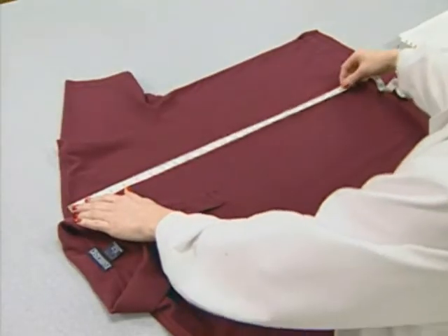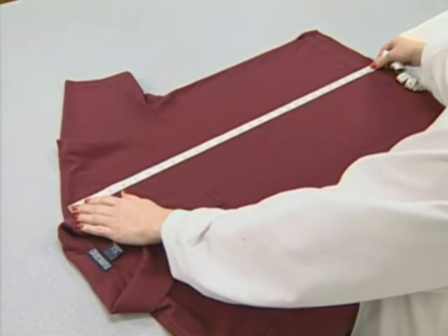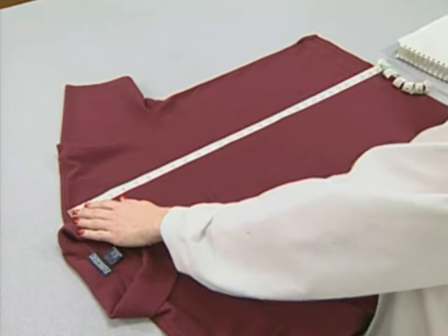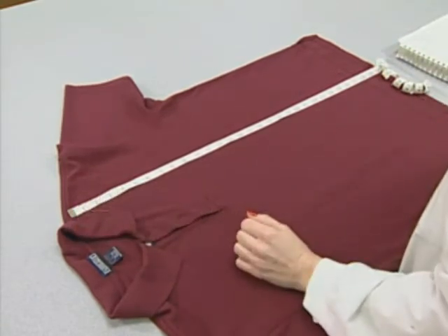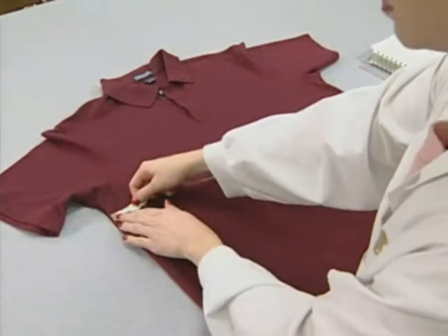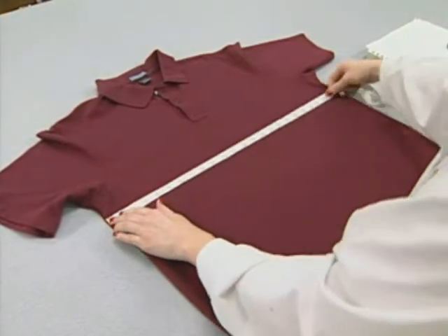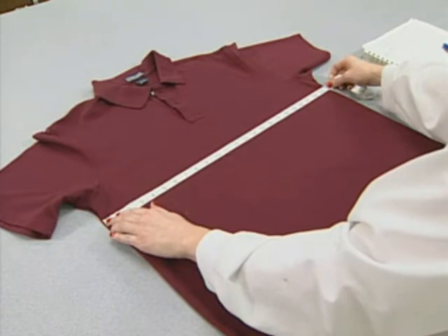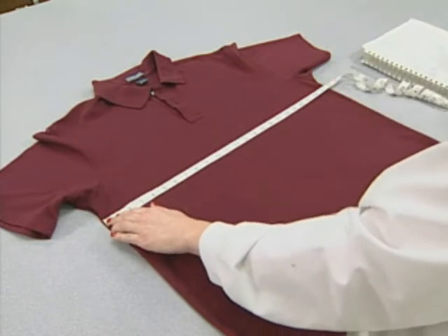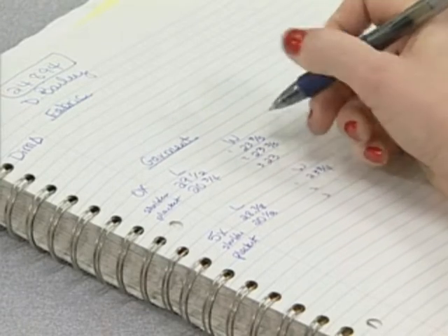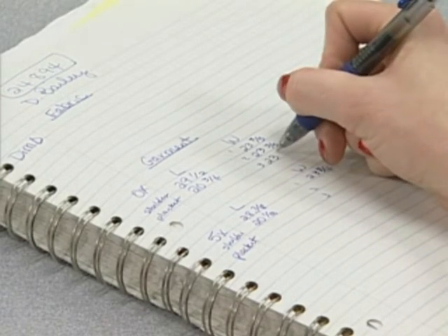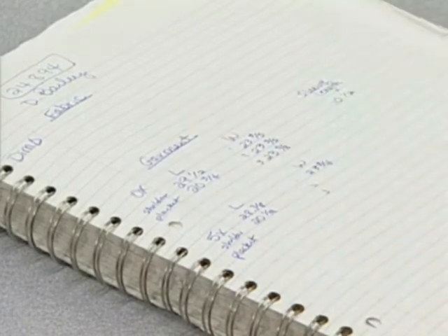The next step is the evaluation or measurement of the change in dimensions. Each specimen must have its benchmarks measured. In knit constructions, the length is the wale direction and the width is the course direction. In woven constructions, the length is called the warp and the width is called the filling. Record the distances or a percentage dimensional change and enter onto a tally sheet or into a spreadsheet.